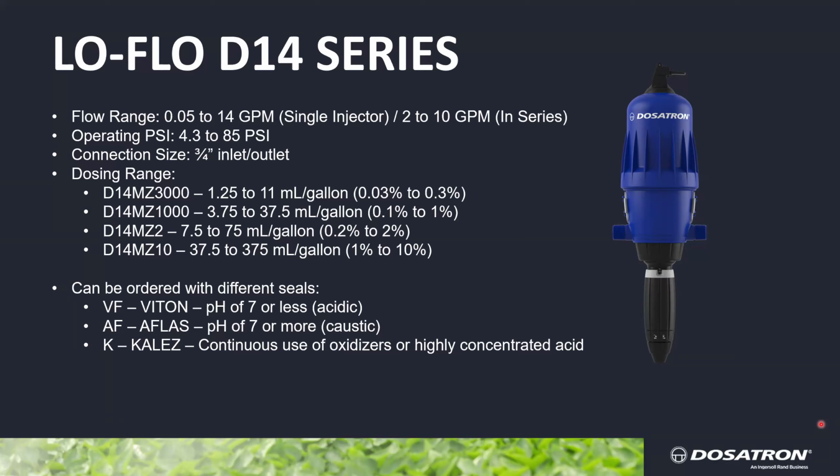Now, when it comes to the world of hydro, we've seen a big increase in pH up over the last 5 years, specifically the last decade, but let's say even the last 5 years targeted. And that's where you've seen more introduction of the Aflas seal. Now, there's only really particular chemistries where the Aflas seal is what we consider necessary at the beginning of ordering. And that really is just to extend the life of those seals, right?